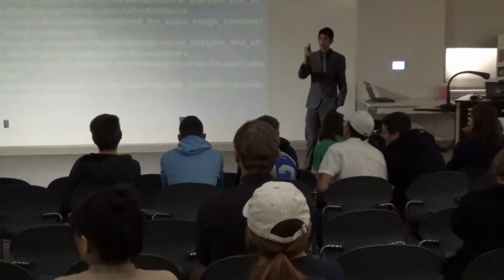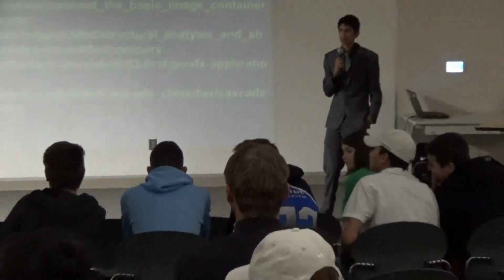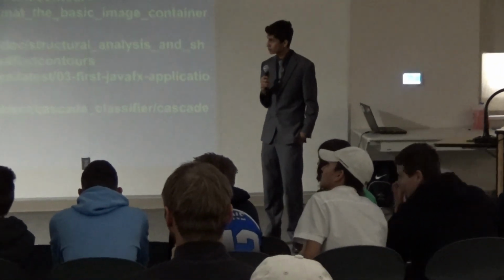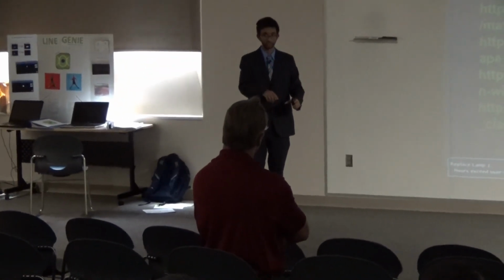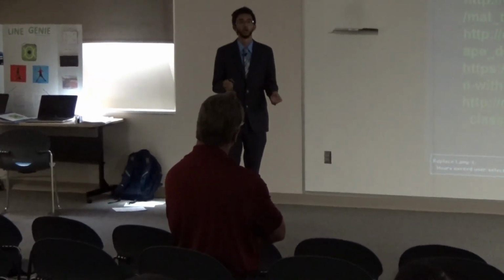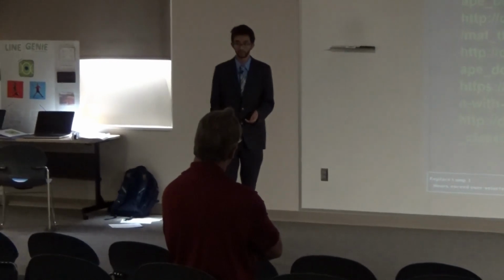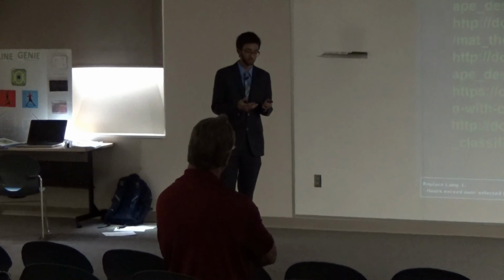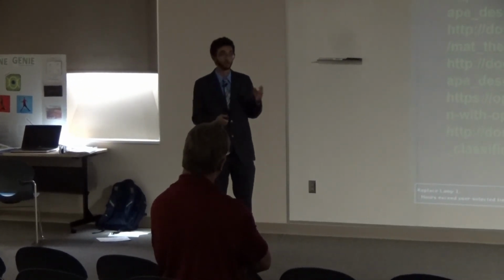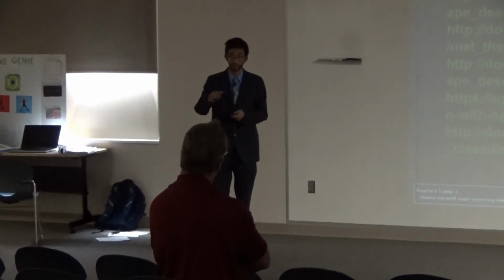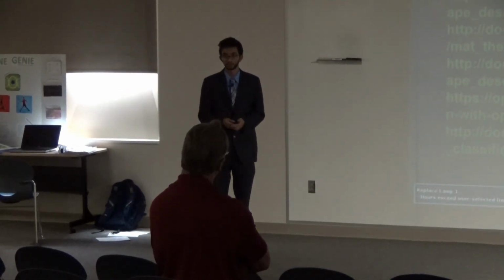Anything else? How did you determine your bounds for your hue saturation values? So that's what I was saying. For the on-touch color function, once I completed that, I literally focused in on a tennis ball and touched the screen where that tennis ball was. That output the color value in hexadecimal, which you can easily convert to hue saturation values. You need a range for that because not all tennis balls are going to be the same, based on how much they're used or how new they are. They could have different shades of green, so you need a range that is acceptable for all tennis ball values.